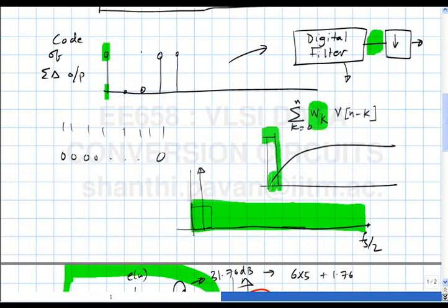And it turns out that in some digital filter structures like IIR filters, because of practical difficulties associated with finite register length, some structures can actually go into oscillation, okay, because of coefficient truncation, alright, which is one reason why a lot of people prefer to use FIR filters, because there is no feedback, it's always feed forward, right. So there is no recursion at all, alright.